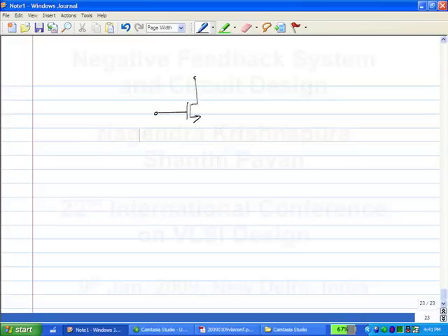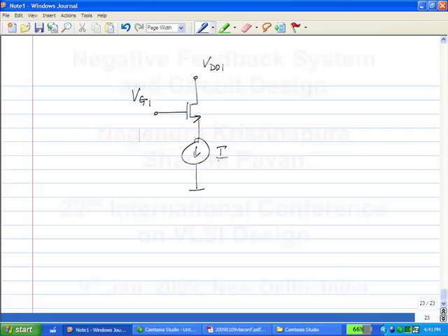So this is IREF. We just discussed that this incorporates negative feedback, where the source current is compared to the reference current and you kick the source voltage in the proper direction. This is a pretty popular thing to do in ICs. However, on a breadboard, on an IC it's very easy to get a current source, isn't it? You take a transistor, make it operate in the saturation region, and then you have a current source.